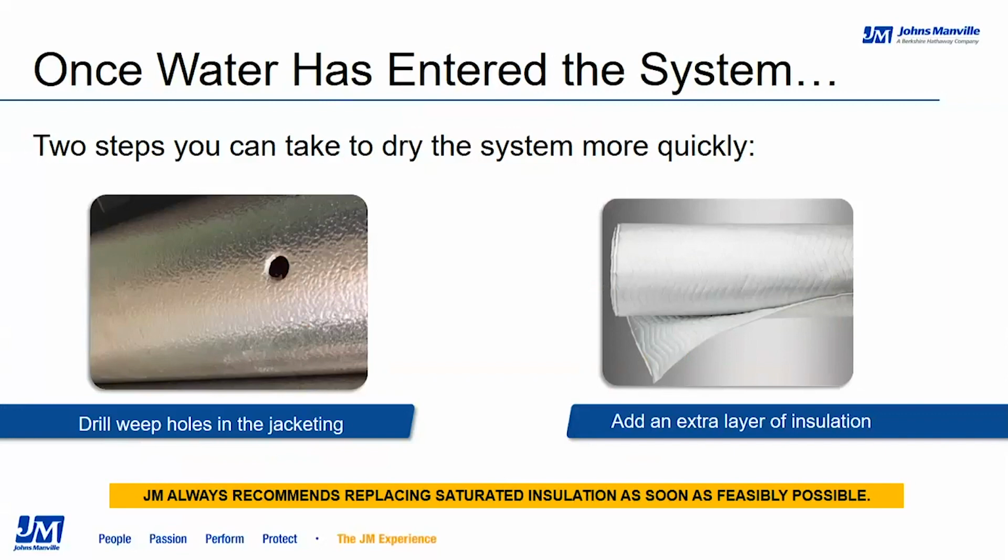Additionally, saturated insulation is substantially more thermally conductive than dry insulation, and it will significantly hinder your process control until it is dry. Second, while we will be discussing the results of recent testing done on weep holes, we don't endorse the use of these practices without the proper engineering analysis for your application and your system. So with that, let's take a look at exactly what weep holes are and what they do.